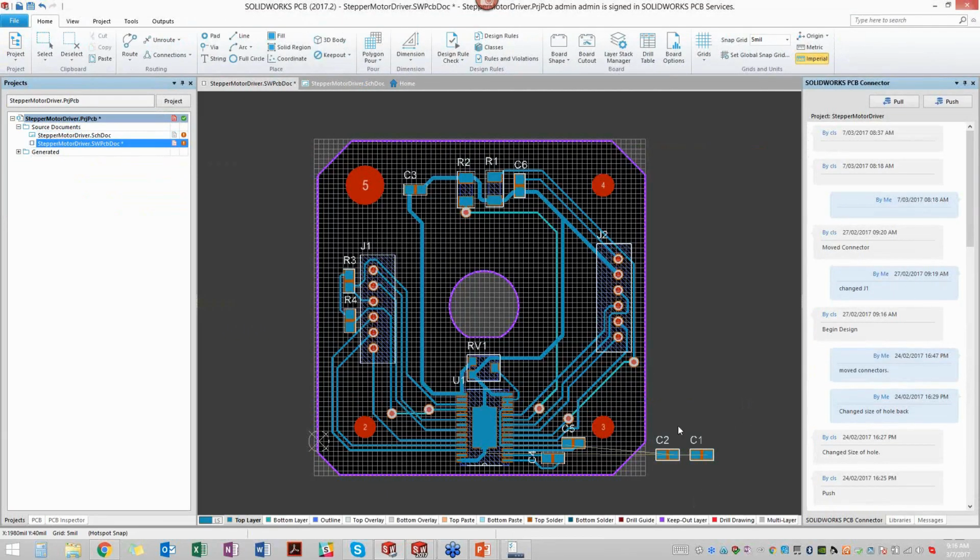Again, moving over to my PCB, and you'll see here that I have my 2 capacitors that I've added. So you'll see that I get the little bird's nest lines, the little spider webs that come along with it. Right now you'll note that there's a red line kind of snapped to that capacitor. What that means is that it's not necessarily a favorable position for that particular capacitor to be in.